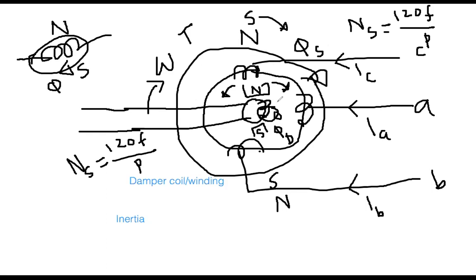But then there is no problem, because this physical north pole, which is attached to the rotor body, has started rotating. So you are fully fine. The only problem is at the beginning. Without the damper winding, a synchronous motor cannot get started. It will just vibrate a little bit in this direction or that direction. Everybody, could you follow me? Yeah, seems fine. Yes. So that's why I was discussing that thing.